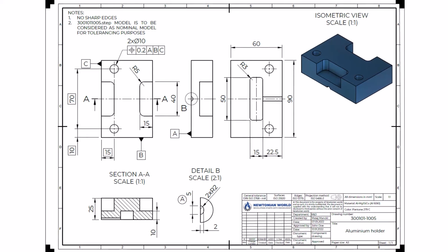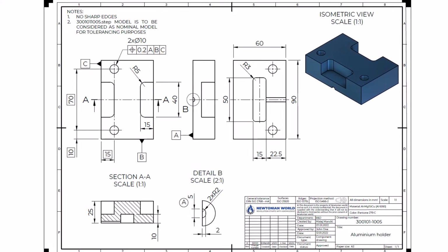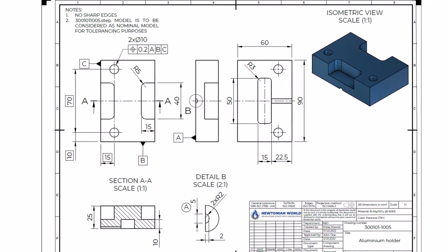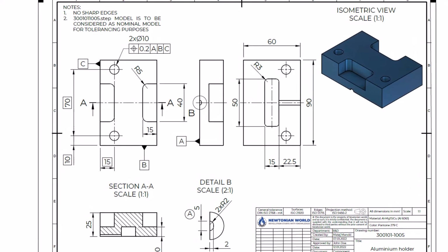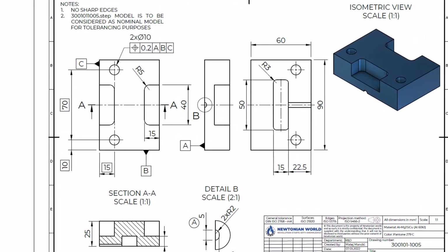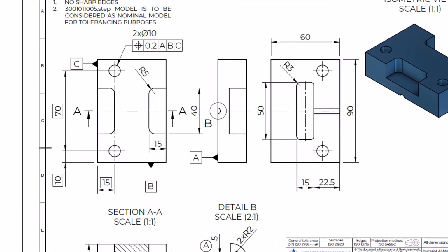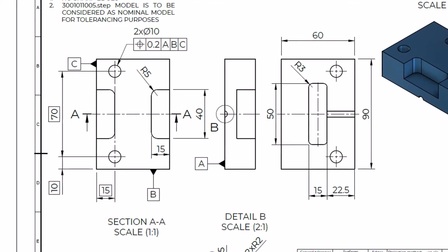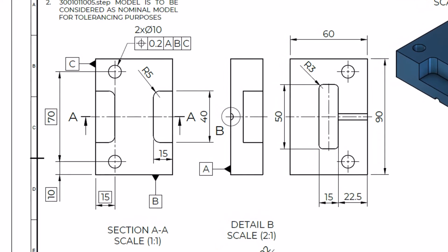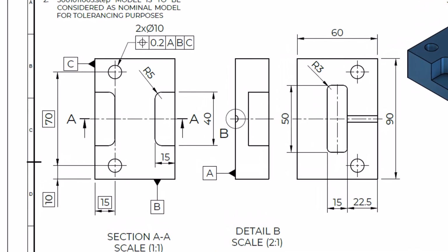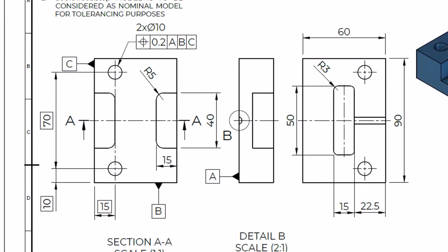It is in the center of every drawing, and it is used for specifying the 3D object to the point that the object is manufacturable. In orthographic projection, the face of the 3D object is always parallel to the 2D plane, paper. This means that the face that is projected is true, there is no distortion of the object's face. There are 6 such views for any 3D object.